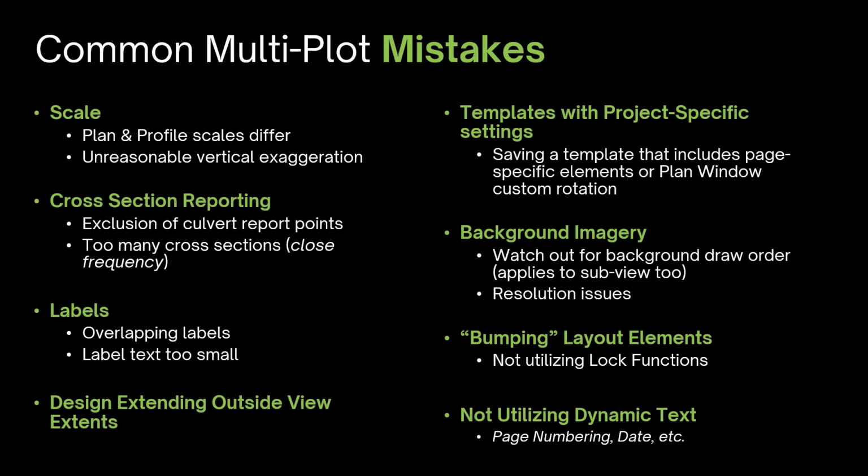Background imagery, remembering that there is a draw order when it comes to background imagery, as well as when it comes to printing, making sure that your background imagery has a high enough resolution to look good. We will show you how to use the lock functions. This helps you to avoid bumping other things within multi-plot. If you're like me and you spastically click every now and then, locking elements, even partially or fully locking, can really help to allow you to maintain that specific positioning in the layout.